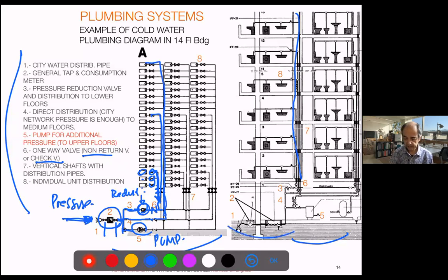And this is the diagram of how it works. The connection to the city, the first connection box, the two valves with the general counter, and then the three sets, right? With the tank to bring water to the pump and to supply the water to each of the floors. You see that we usually need a shaft to bring those pipes. This is very economical because you need very few pipes.